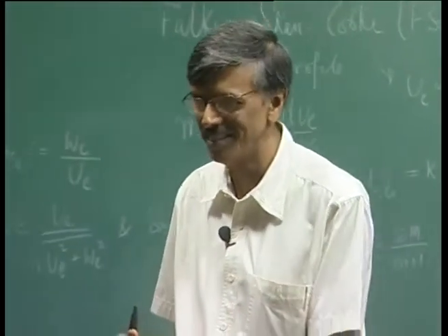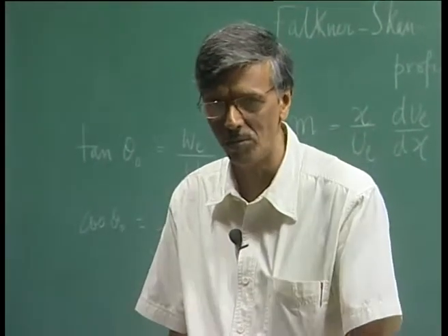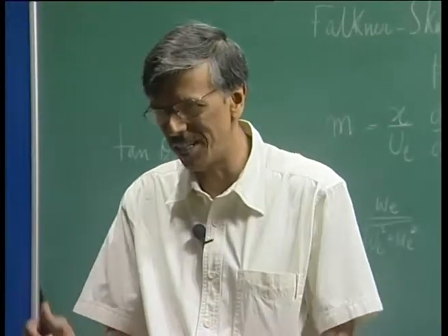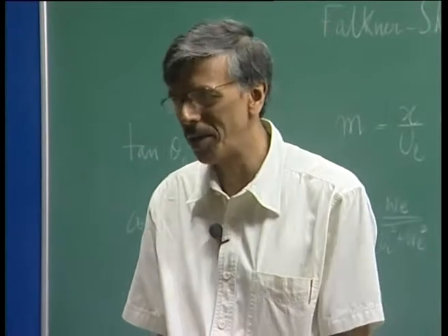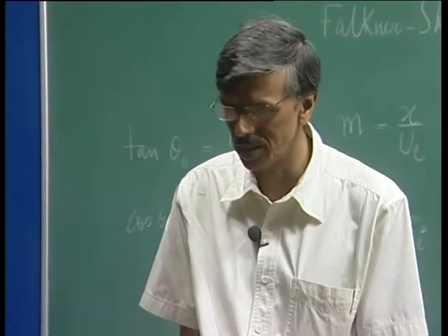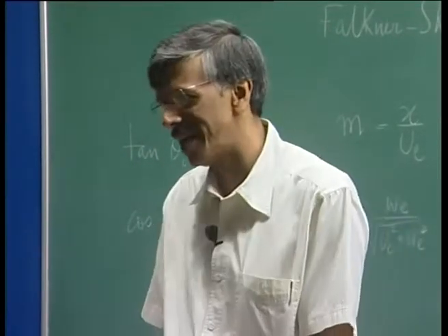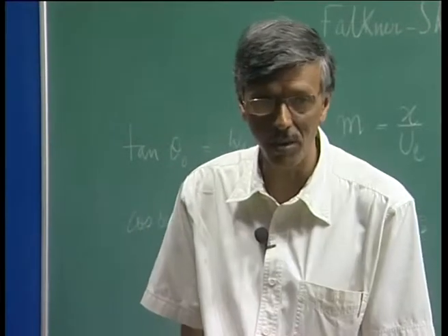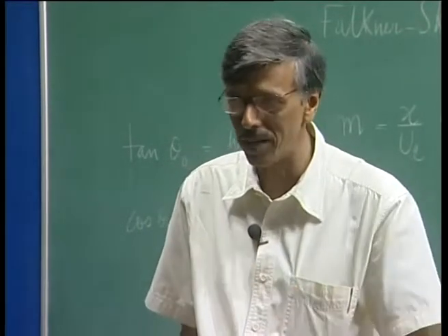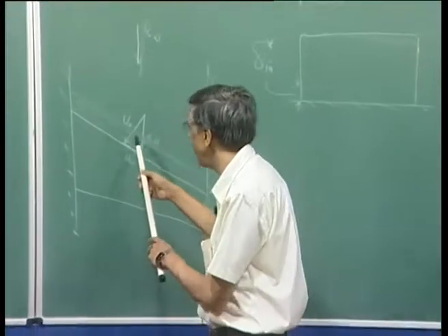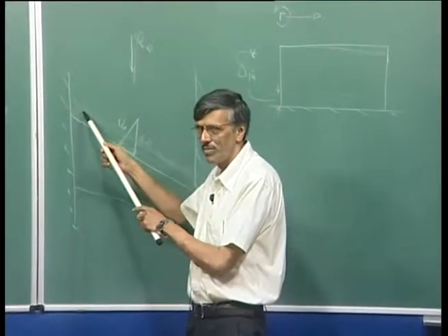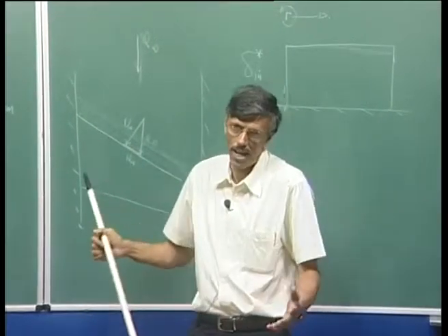We have been talking about it all through, that there is no such thing as generic instability. We have seen for pipe flow, the flow can be unstable at 2000 Reynolds number based on diameter. It can be even at 100,000, depending on how you quench the background disturbances. So, here also the boundary layer may be ready, but if I do not allow these convecting vortices to be created, I am done.